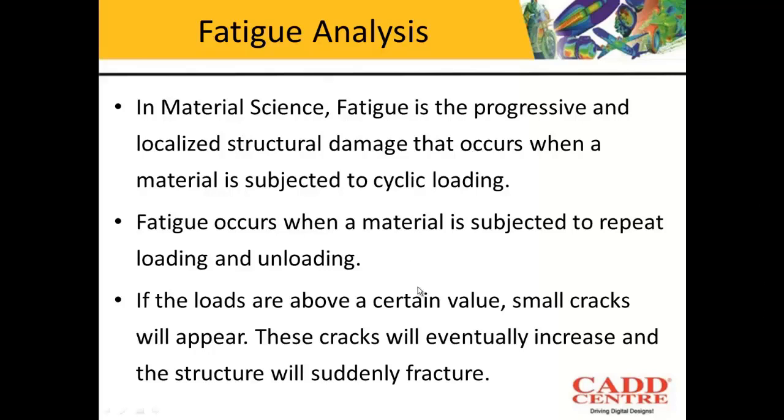Okay. Now when this is happening, the model starts to deform. So when you are applying the cyclic loadings on a design, the model starts to deform, and after some cycles of loading, small cracks start developing in the design. These cracks then gradually start increasing, and suddenly the structure will fail.